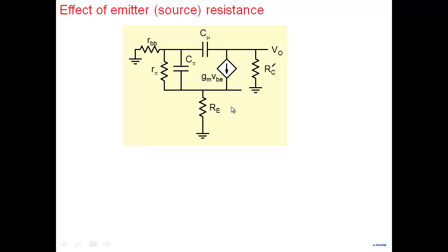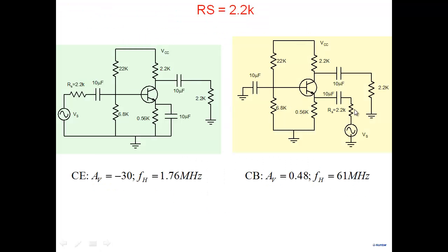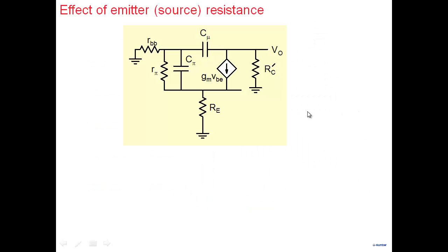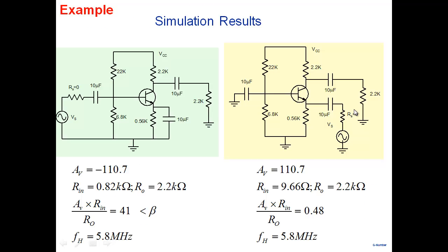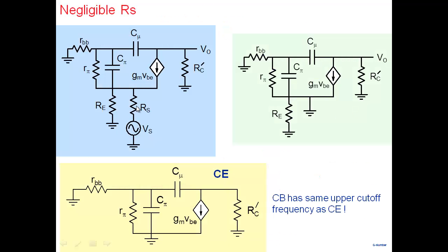So now, remember when I put a source resistance here, so what is really happening? When I put a source resistance that you see here, go back to the equivalent circuit. When I put a large source resistance here, then what would happen is I'll not go here. What I'll end up with when I remove Vs, Rs will come in parallel with Re. There'll be a resistance here, Rs in parallel with Re. While in common emitter, there will be no resistance here. Are you seeing the difference?